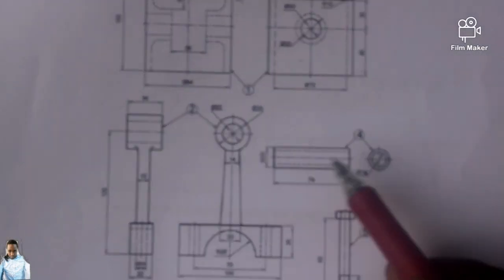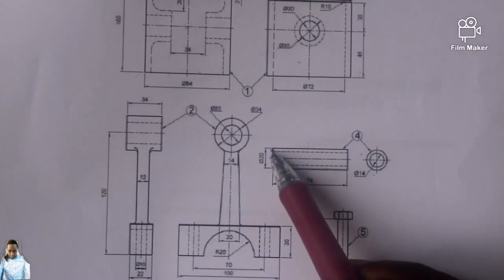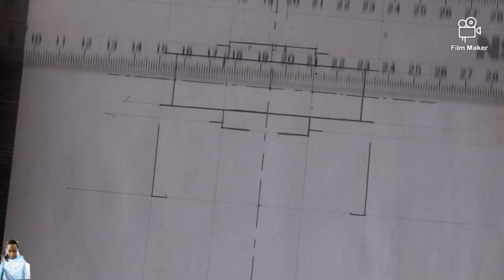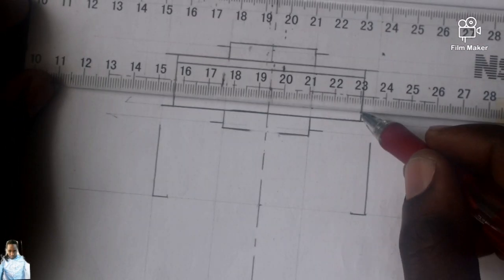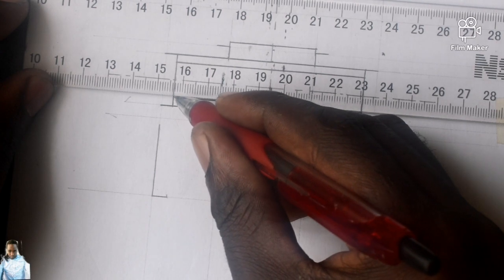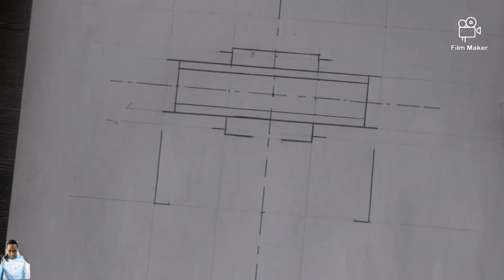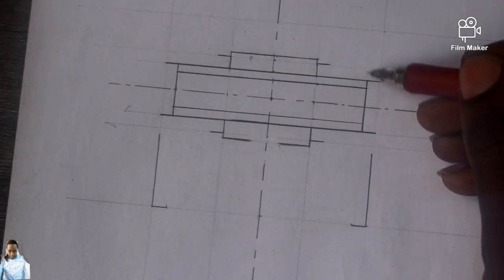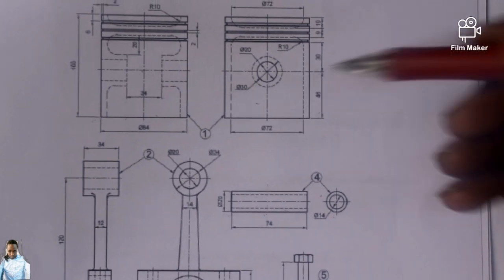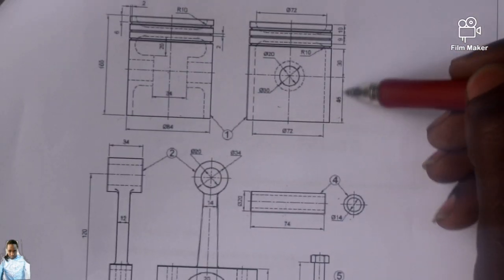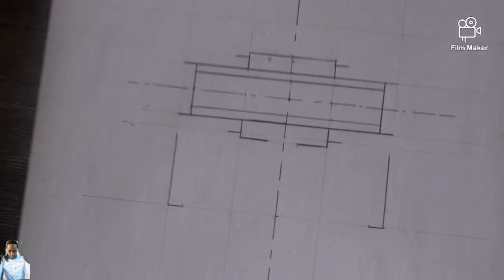So these hidden details of item 4, they're going to change to being solid. So remember that this is the center, this is the hidden detail. So which means this line is going to change dark, and this one dark. So item 4 is already there. You see this one. So which means I can go up now without fear or favor, up there by your item 1. From here going up, you can go up without fear or favor.